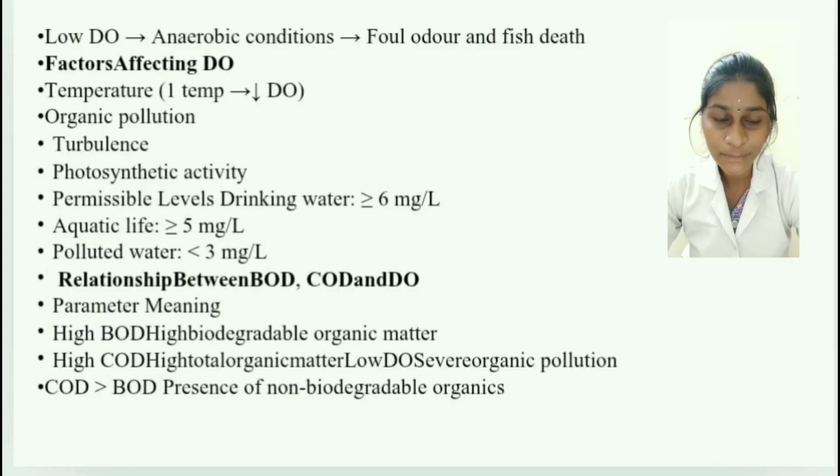Then the relationship between BOD, COD and DO. High BOD means high biodegradable organic matter. High COD means high total organic matter. Low DO means severe organic pollution. COD greater than BOD indicates the presence of non-biodegradable organics.